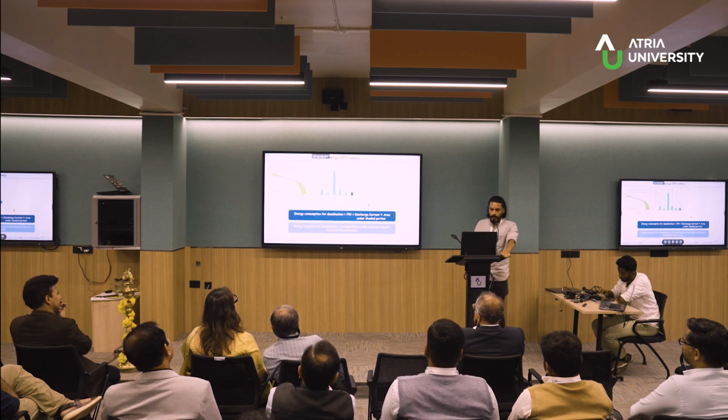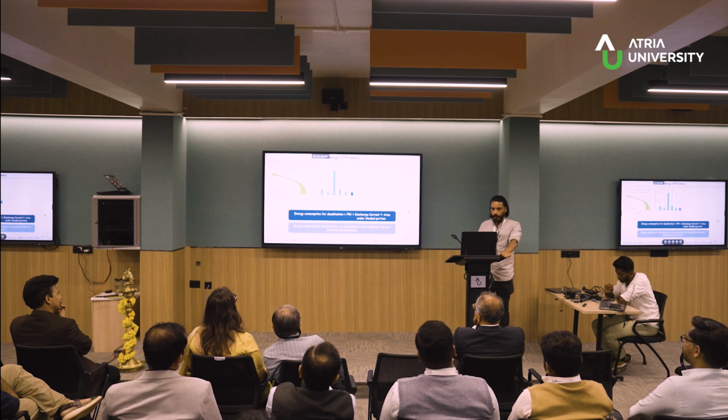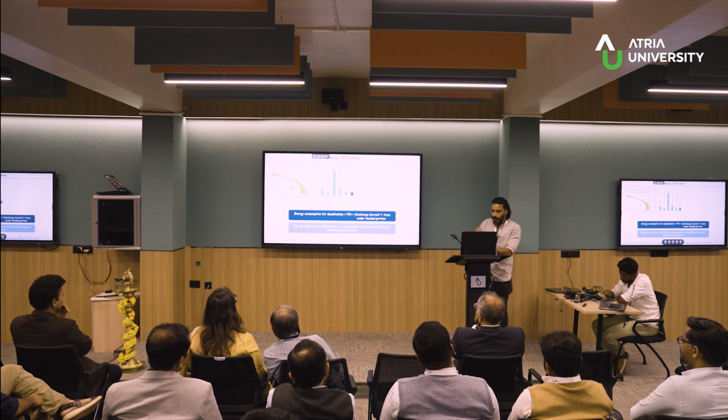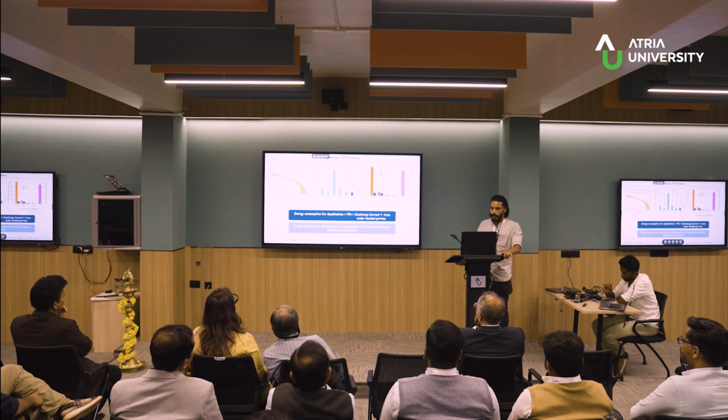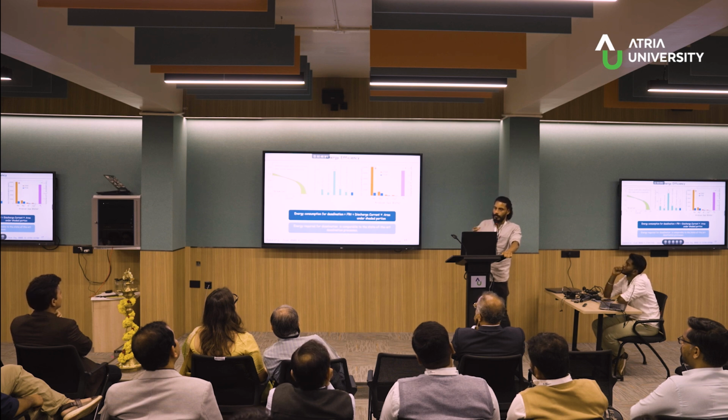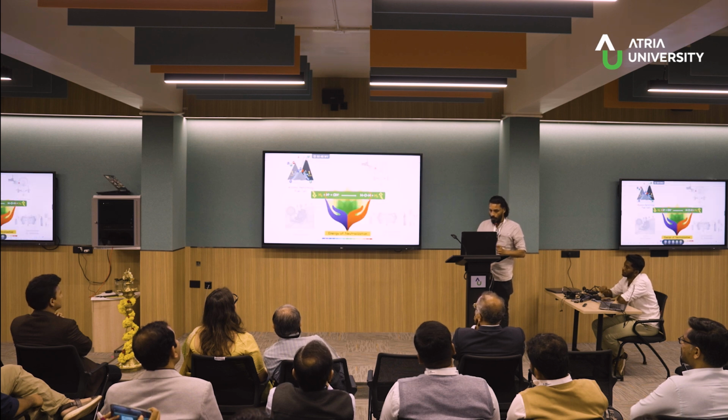We also computed the desalination efficiency by designing two types of devices, one with the middle saline compartment and one without that. And the difference should correspond to the energy invested for removing salt from saline water. That is close to what is reported in the literature for the best RO process. And we could also utilize this approach for removing salt from real seawater collected from the Arabian Sea, and therefore this electrochemical neutralization provides a lot of opportunities.